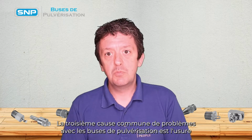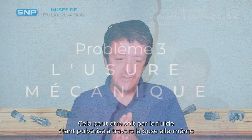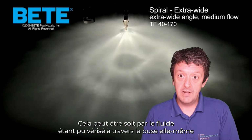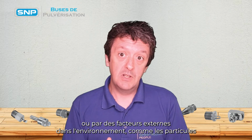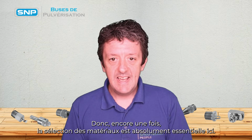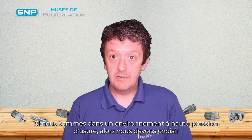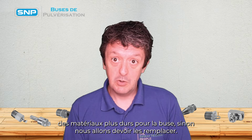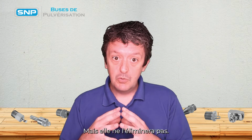The third common cause of problems with spray nozzles is wear, and this is mechanical wear. This can either be by the fluid being sprayed through the nozzle itself or by external factors within the environment like particulates within the gas flow. So again, material selection is absolutely key here. If we're in a high pressure, high wear environment, then we need to select harder materials for the nozzle, otherwise we're going to be replacing them. Material selection will reduce that, but it will not eliminate it.